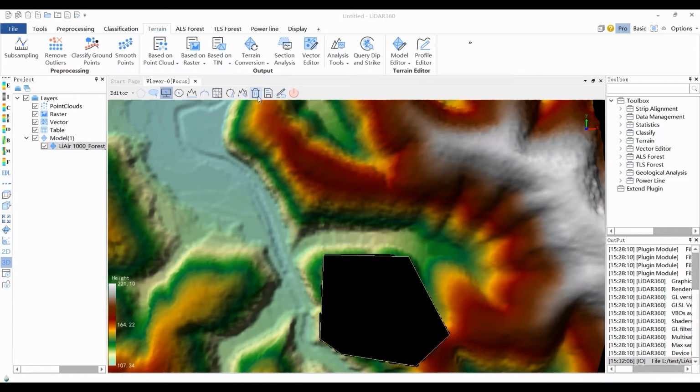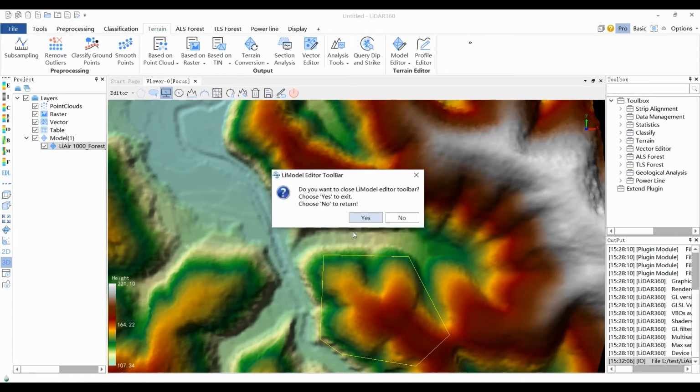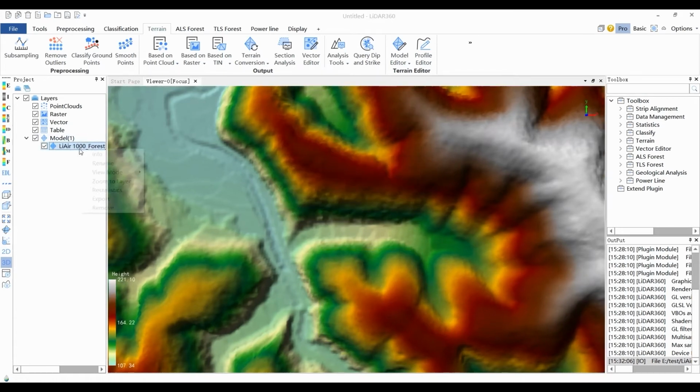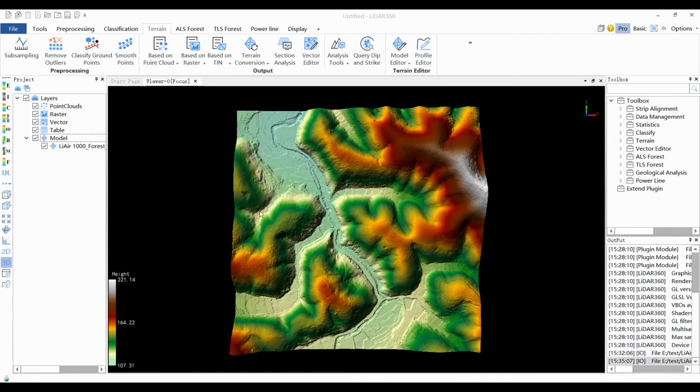The LiDAR file is generated by the irregular 2.5D triangulation model based on the point cloud. It can improve quality of contour lines by editing operations, including flatten height, smooth height, vertex addition and removal, etc. LiDAR files can be edited by using the LiDAR editor.